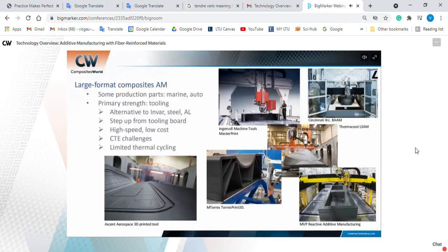Yeah. All right, Ginger, what range of tow can be ultrasonically infused with a PLA or other, and has any work been done or might be planned for PEEK or other high-strength thermoplastics? So like I said, right now, the first tests were done on 12K and 24K. However, their goal is to go all the way up to 50K input tow and spread that. As far as what they're doing with PEEK, I don't know. Because DLR works across the space and aircraft segments as well as other segments, I know that's in their wheelhouse to look at. I just don't know what they're going to do. So I can ask that question and see if they're going to do PEEK and PEKK and PEK as well.